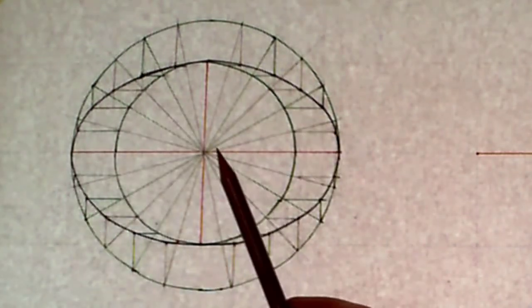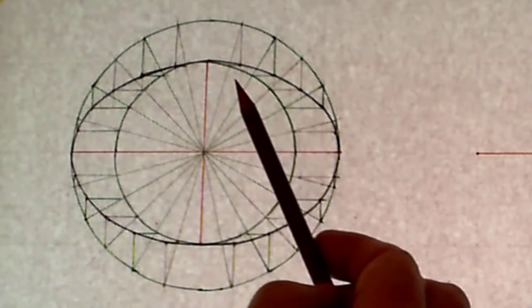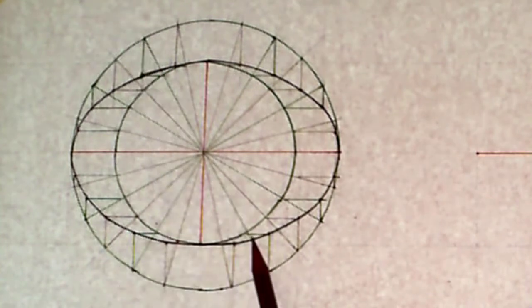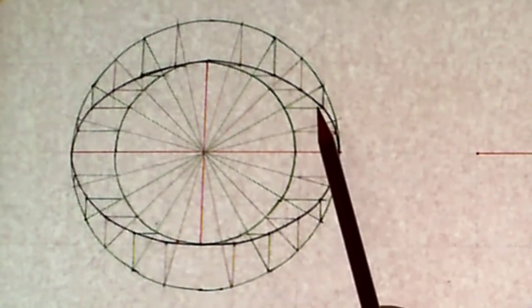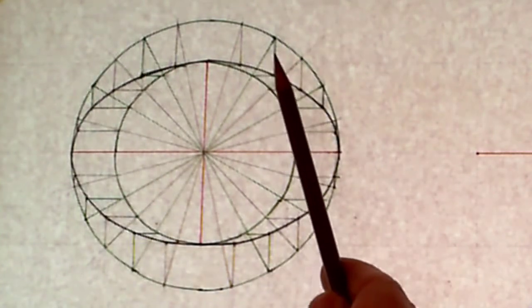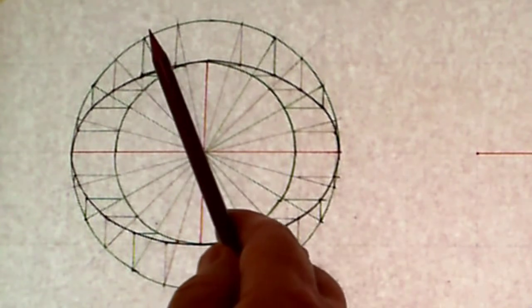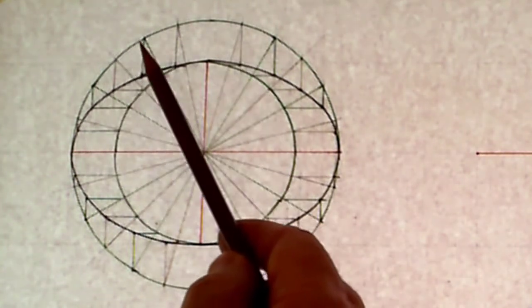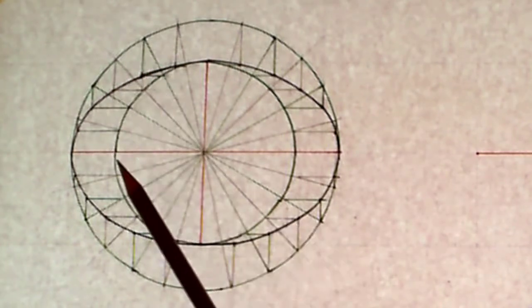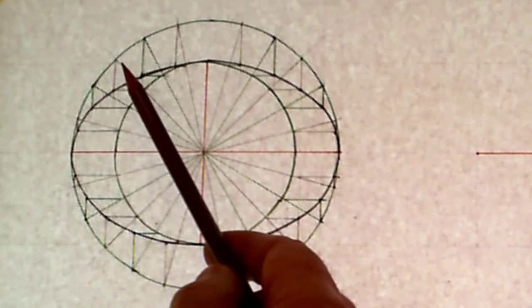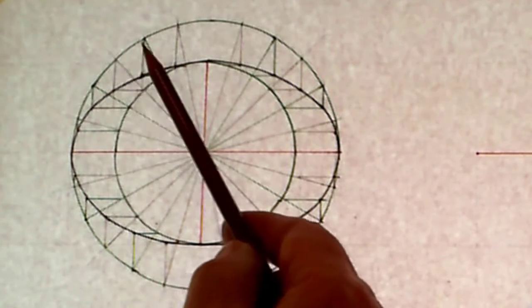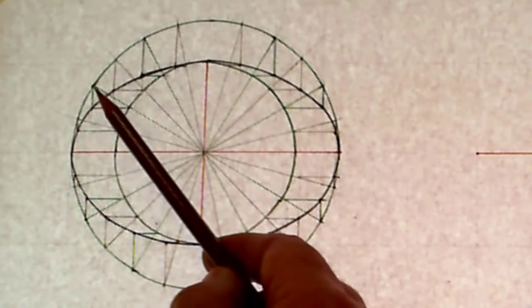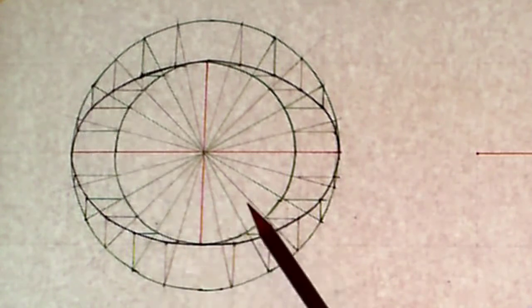Okay, so you've got the major axis, the minor axis, okay, and you've got division of the 360 degrees with regards to the two circles. I've used 24 different intervals using 30-60 degree set square and a 45 degree set square, and then getting the 15 degree interval here and stepping it off each side from the 60 and from the bottom of the 30 to establish the other points.